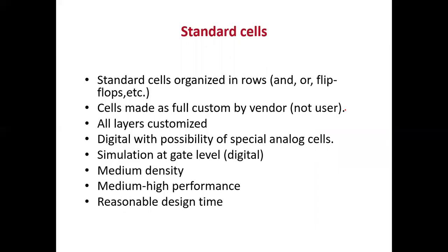Then coming to the next part, that is standard cell. Standard cells are organized in rows, and gates or flip-flops, etc. are there. Cells are made as full custom by the vendor, not by the user. All layers are customized. Digital, with the possibility of special analog cells. Simulation at gate level.